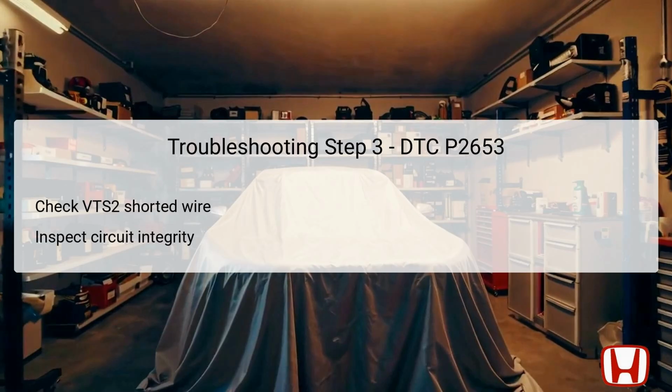The diagnostic data indicates that you should check that the resistance reads more than 1 mega ohm in this state. If the reading is below this threshold, there could be a short in the circuit, which would necessitate further inspection and potentially repair of the wiring. Verifying the integrity of the circuit is essential to confirm that the signals can flow unimpeded between the solenoid and the PCM.